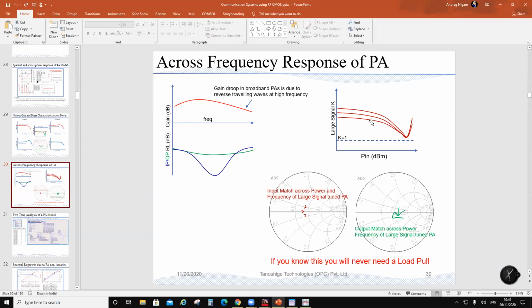For example, an Astra X band amplifier. You go and look at their data sheet. 40 dBm, well and fine. 40.1 dBm, it will blow up. We cannot guarantee you. It is specifically written in their data sheet: 40.1, it is outside my scope of data sheet, it will blow up, we don't guarantee that. What kind of designer are you? That 40 will be okay and 40.1 will be blowing up. This is what Astra is, because they are using optimizers. Their engineers are using optimizers for tuning. They don't think in terms of stability and ruggedness and all that.